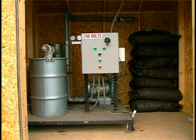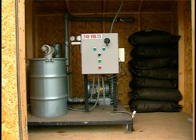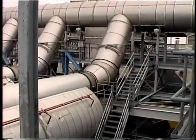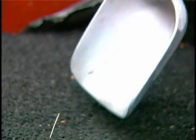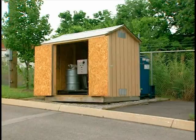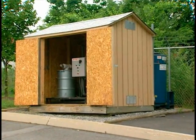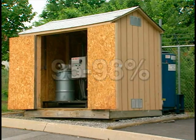In adsorption processes, gaseous contaminants are removed from a gas stream by transferring them to the surface of a solid adsorbent. These adsorbent materials include silica gel, activated alumina, molecular sieves, polymers, and activated carbon. The most common material for the adsorption of organic pollutants is activated carbon. A properly designed activated carbon system is generally capable of removing 95 to 98% of an organic contaminant.